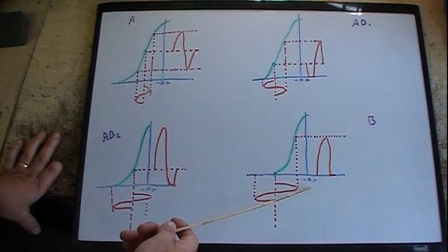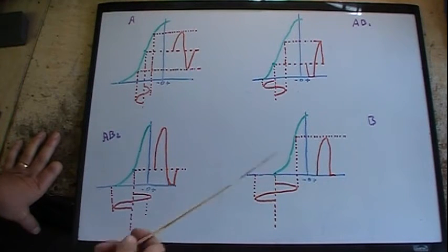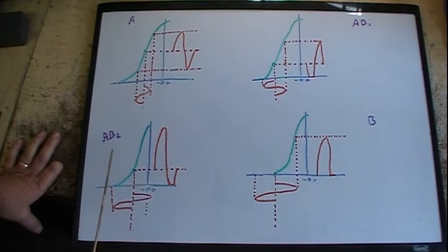The only thing is, and this one really, to get the maximum gain out of a Class B, we actually do run the grid a little positive on it too, on the positive peaks. So on both of these, there's going to be points when we do have some grid current. We got to get it from somewhere. So one of the problems is where to get it from.